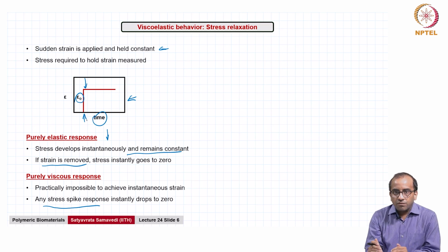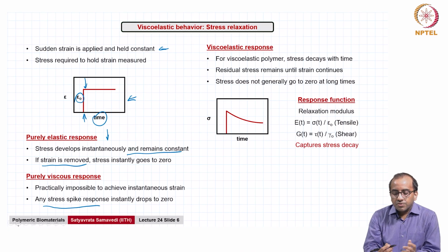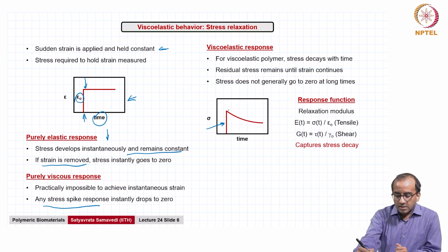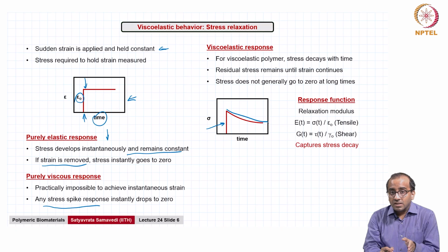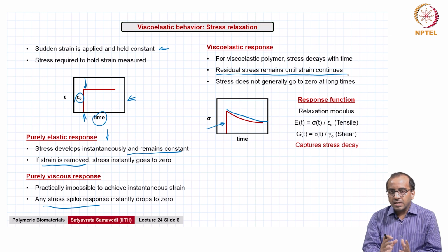Now, what is the scenario for a viscoelastic response? Here what you see is that with time the stress is going to decay. Again, remember, the deformation is held constant with time, that is not changing. For a constant deformation as a function of time, the stress is going to decay or reduce within the material, right. And this residual stress remains until the strain continues, and even at very long times the stress typically does not go to 0, but again that depends on the type of material, the temperature you are operating at, etc.